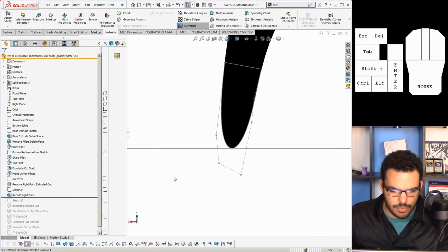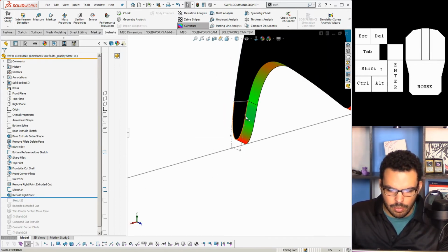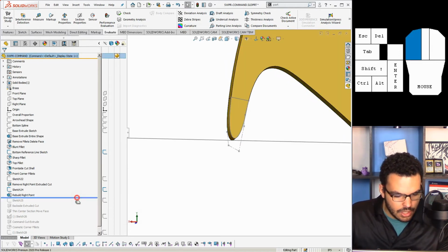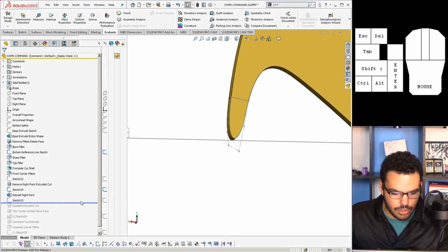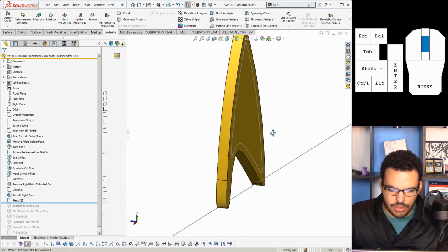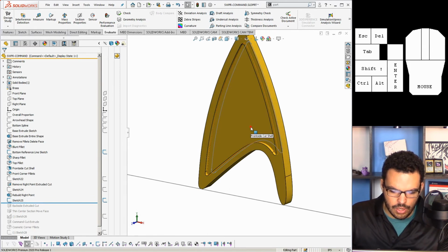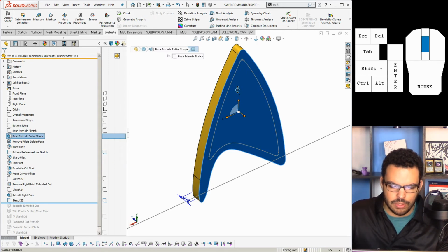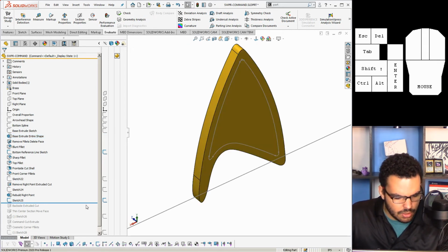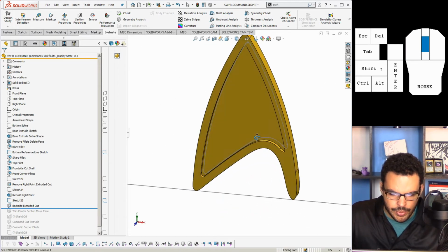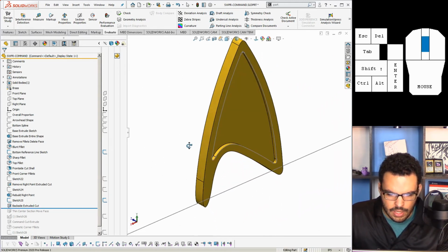So the sketch seems to be happy. The curvature still looks great, so I'm gonna consider that fixed. And let's keep going. This one also has no label. That's interesting. Looks like he converted this face onto this back face. Interesting technique. And then he extrude cuts this. That is something I think could be done with a mirror.